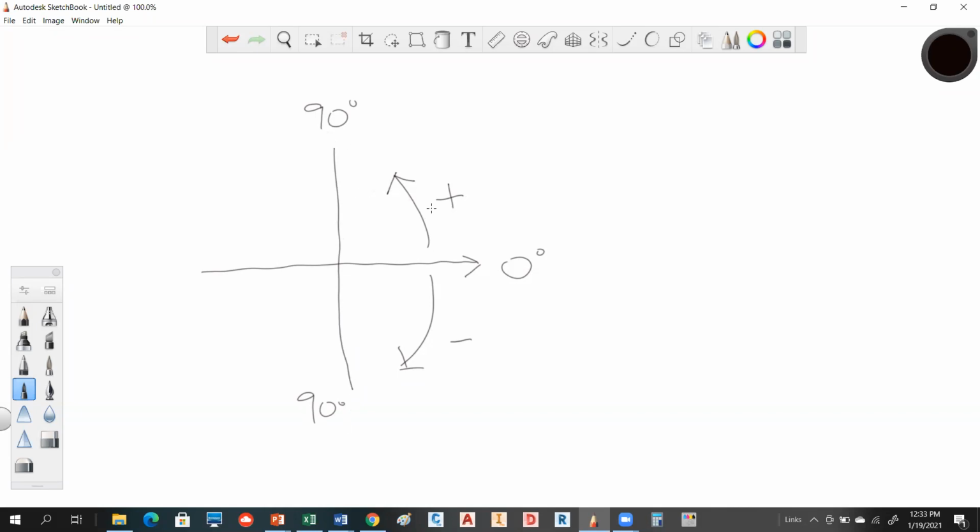Most modern surveying instruments don't use this technique at all. This is an old style of angle. What they use is primarily what's called the zenith angle. If you're looking straight up along the plumb bob string into the sky, this is your zenith.